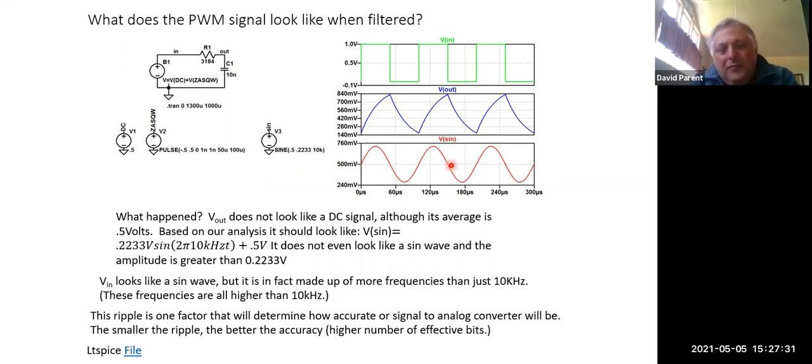So meaning if I had a square wave at 1 megahertz, right, not only would it not work, because the fundamental frequency would be at 1 megahertz if the gain bandwidth was 1 megahertz, but it's got all those extra frequencies on top of it. And so, yeah, even though these are efficient on pins, square waves come with a lot of higher harmonics.